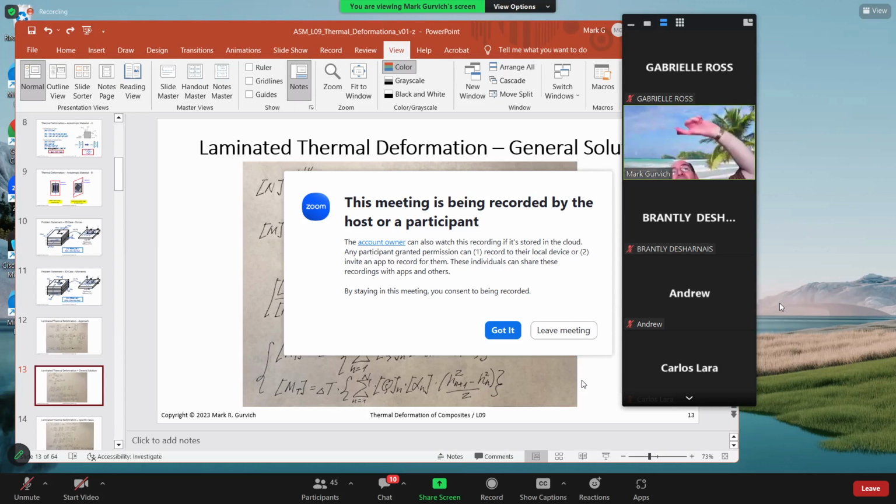One side, when you were in space, was close to minus 150 C, and the opposite side, because of the sun, could be heated up to plus 150 C. So in this panel you have a temperature gradient through thickness of almost 300 C, maybe close to approximately 600 degrees Fahrenheit. It's huge, and because of that, the entire system could buckle.